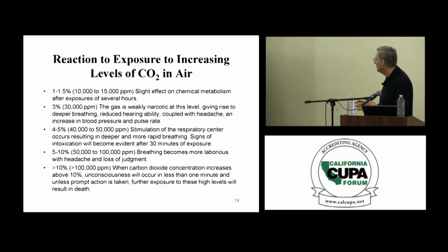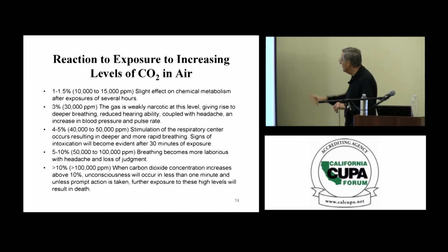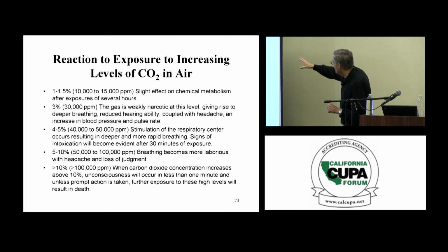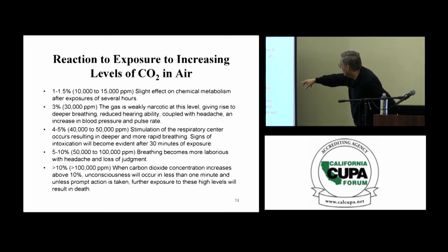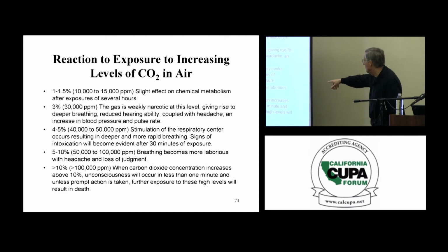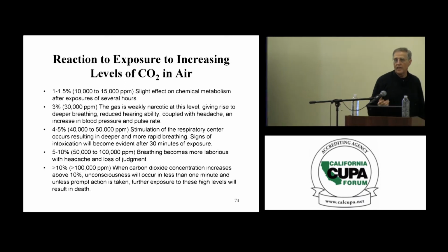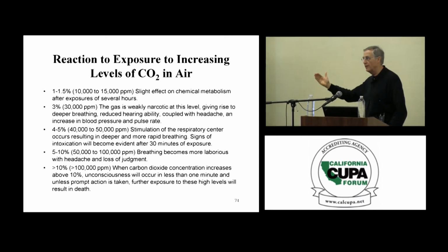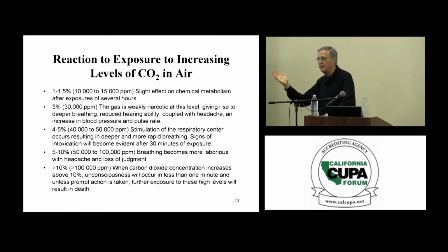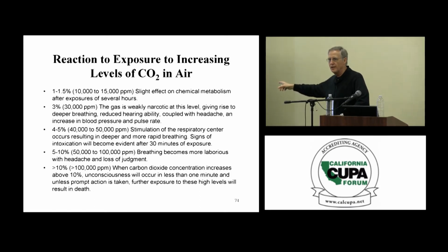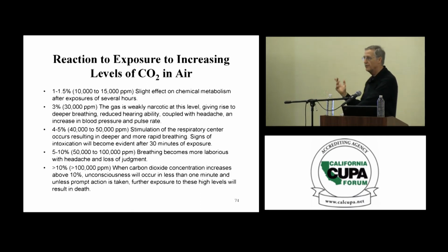And these are the levels. If you get to 1 to 1.5%, slight effect on chemical metabolism after exposure. If you get up to 5 to 10%, breathing becomes more laborious. Above 10%, you could die. And at 10%, the oxygen level is still fairly high, so you can be above 19% or so. So you would not have an asphyxiation hazard in terms of dying from lack of oxygen, but you could still die from CO2 intoxication. So that's why in terms of inerting, CO2 is a lot more dangerous than nitrogen from that perspective.